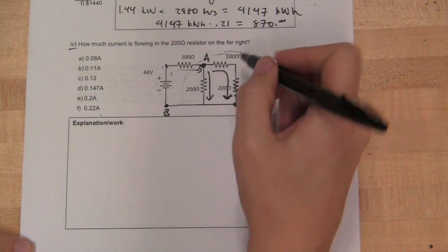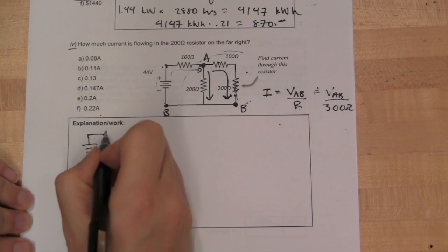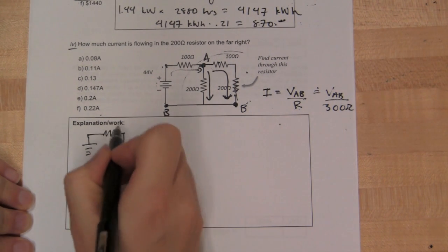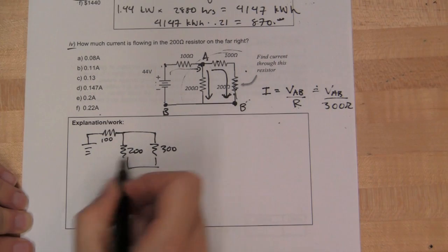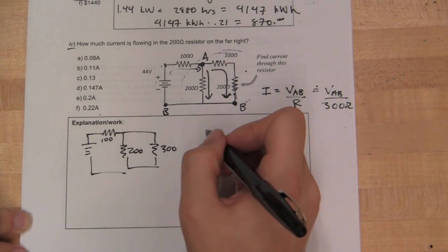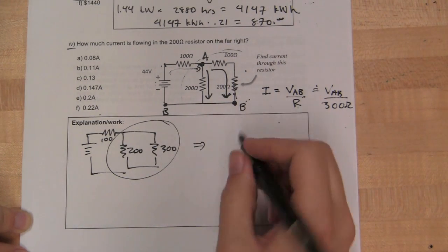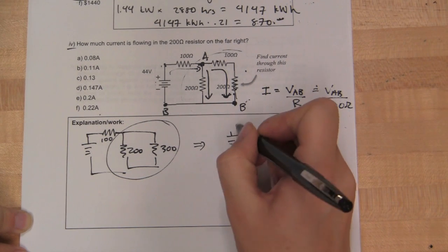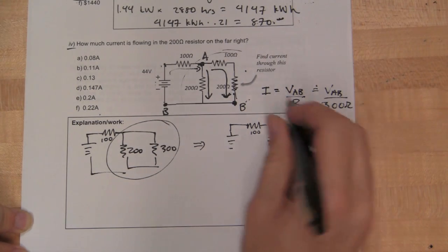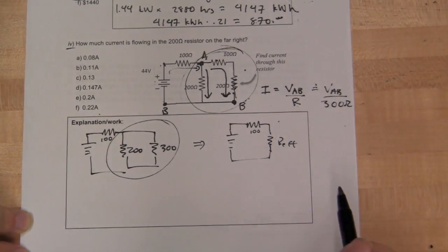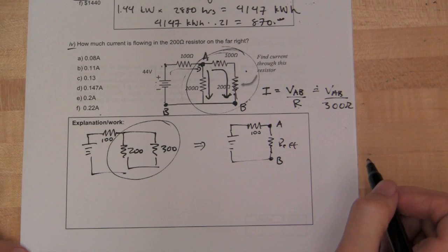So let's see. What we have here, we have a 300 ohm. Let's redraw the circuit. So we have our battery. We have 100 ohms here. We have 200 ohms here, and an effective 300 ohms here. So these two resistances are in parallel. So if we redraw that with a new effective circuit, we'll have a battery, 100 ohms, and then this R effective from this whole side of the circuit here. And we want to know what that is. And now on this circuit diagram, the points A and B are these 2 points.